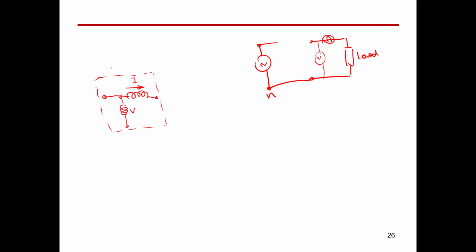So by the end, wattmeter will have three terminals, as you can see. Two terminals to be connected in series with the circuit to measure the current, and the third terminal to be connected in parallel with the load to measure the volt. And internally, it will calculate the power. Okay, so I'm not going to discuss internally what is happening in the wattmeter. So the wattmeter is already something called moving iron device.